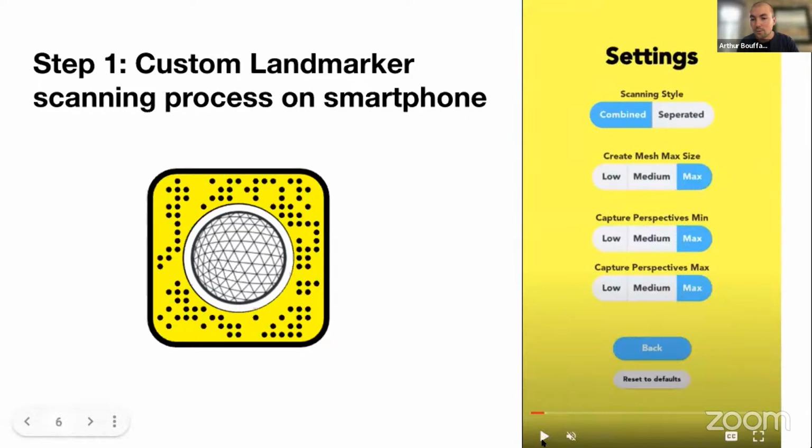The first thing that you want to have a look at is the settings here. There are not that many things in there, but a few things that you should be considerate of, like the size of your mesh and the size of the perspective that you want to capture. These settings will vary depending on what you want to capture. For instance, if you want to get a statue with a lot of detail, you might want a bigger mesh size. So I usually recommend maxing out these settings, though that will also depend on what you're trying to build.